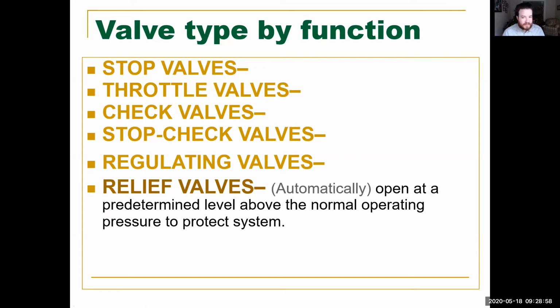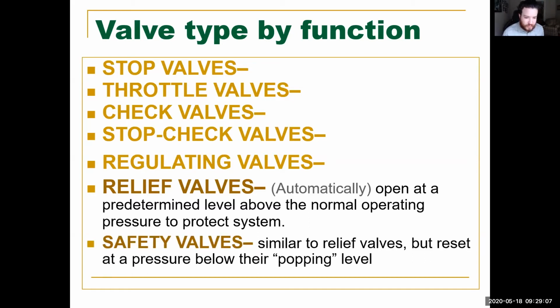Then you have relief valves. Relief valves automatically open at a predetermined level above the normal operating pressure to protect the system. All right. Then you have safety valves. Safety valves are similar to relief valves, but they reset at a pressure below.